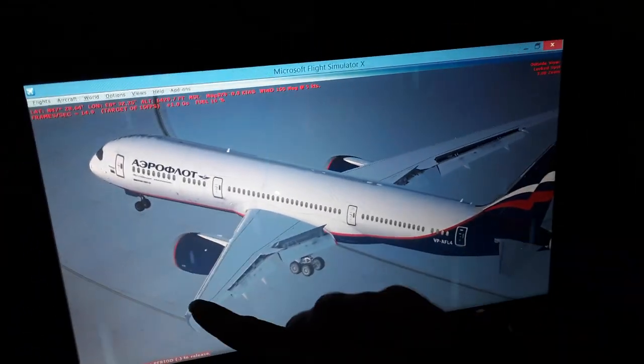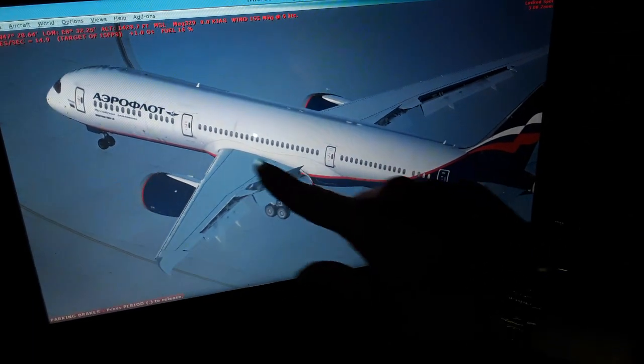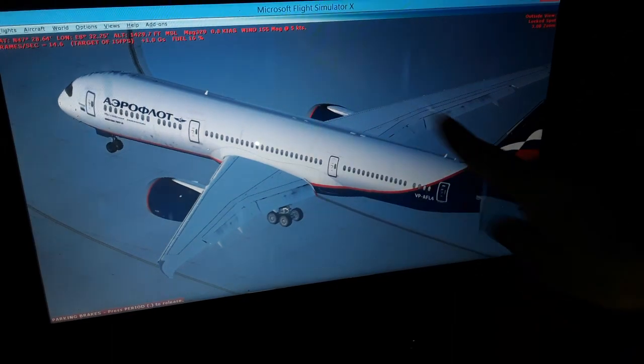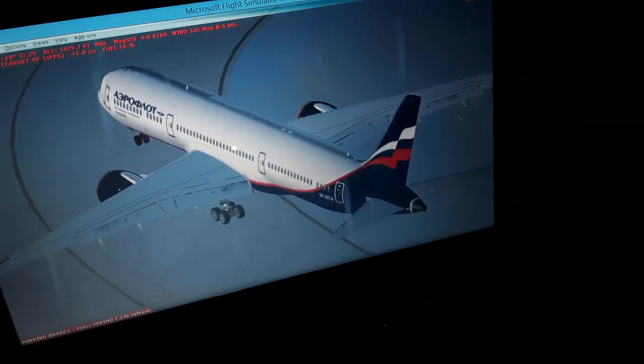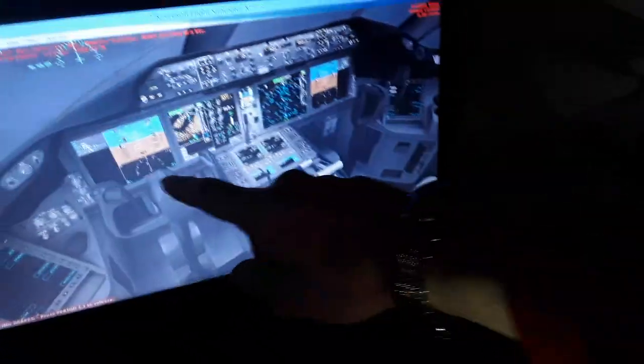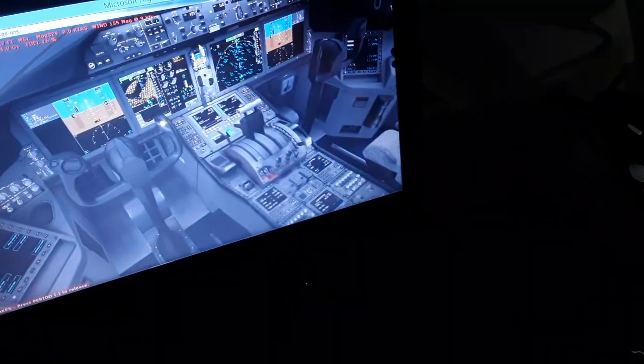So we have here the main aerodynamic chord where the maximum aerodynamic lift occurs. Also the center of pressure is moving back and forth, and on the top surface of the wings, the airflow becomes detached when we fly, and the stall begins. So when we stall the aircraft, we have to pay attention. We need to push the side stick down, or the yoke, and advance the thrust levers to increase the airspeed.